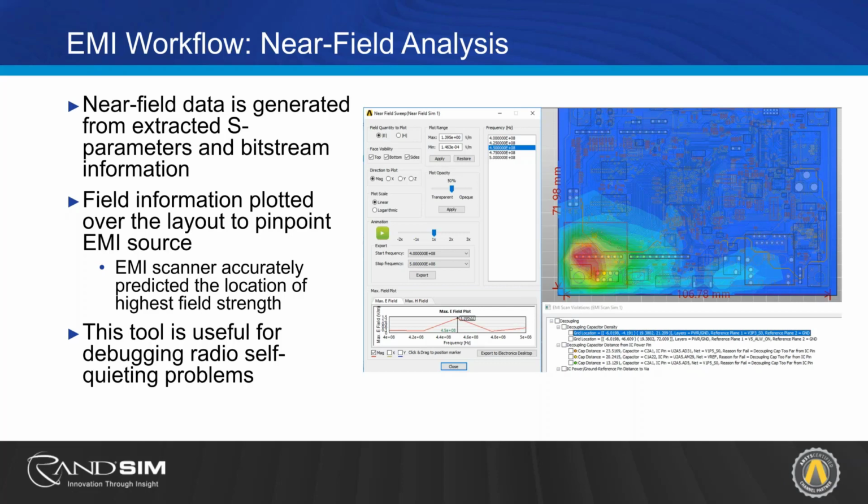The value versus time output is much greater in the EMI workflow within SIwave, so that you could be running multiple simulations throughout the day as you're making changes. And because the importing of the CAD files or even changing components on the fly, like that decoupling capacitor example that I shared, all those things can be done within SIwave, and the simulation is in the matter of minutes, versus in HFSS, the simulation could be hours or even days.